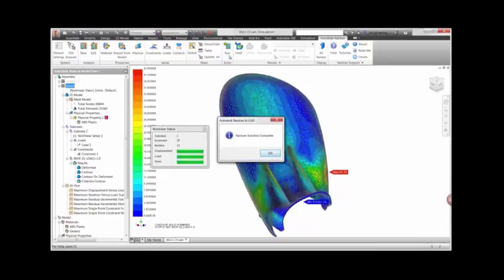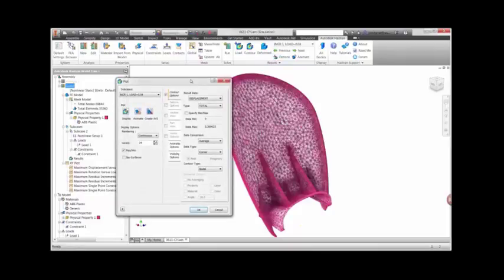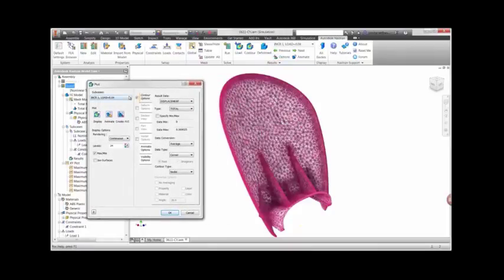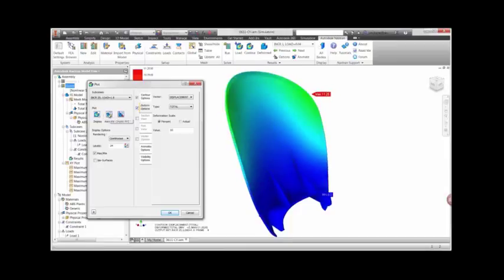We can already see that the highest stress in the model is getting close to yield even before the solution is complete. There are many options available for results. The display plot will help us to determine how far the guard is deflecting. We can view the results at any point during the load. This may come in handy when applying a variable force that is loaded and unloaded. Here's a view of the displacement plot at 10 times the actual deformation.